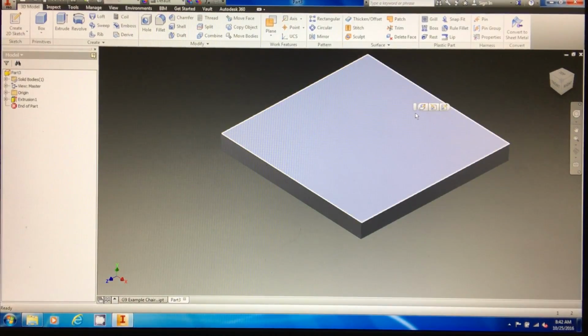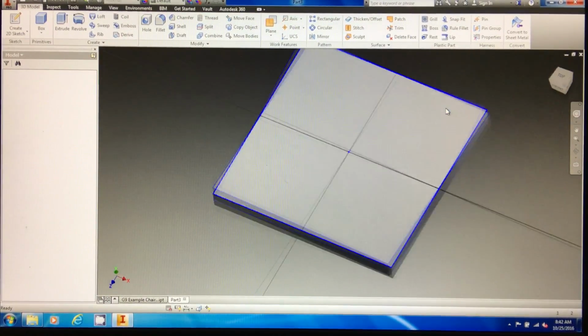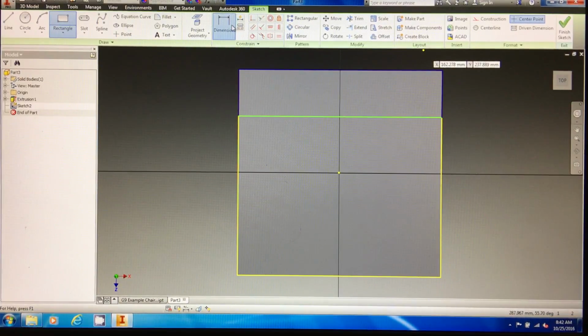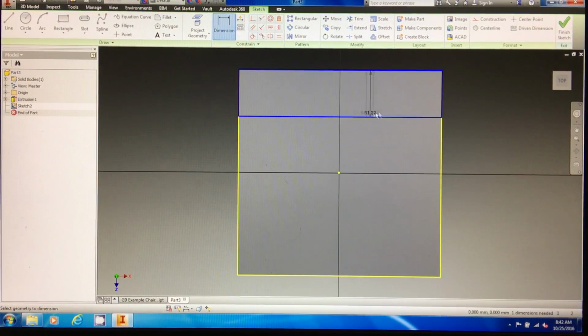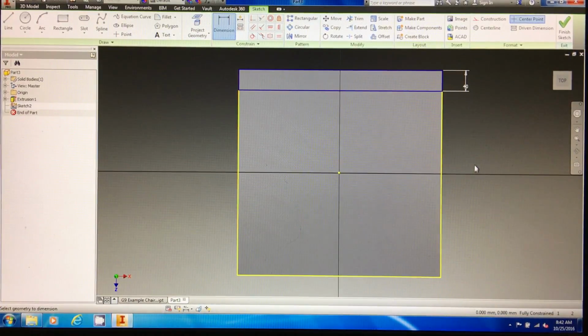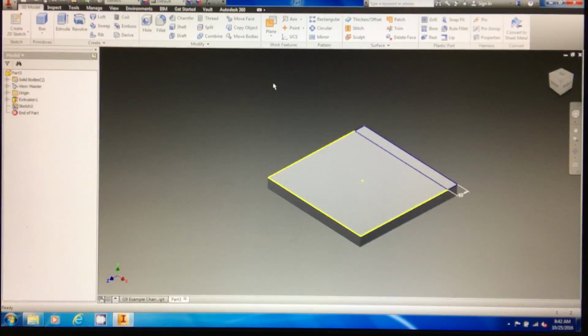Now this is the seat of the chair, so we're going to have a back going up here somewhere. If I click on this top surface, I've got an option to create a sketch. I'm then going to create a new rectangle, but this time I'm going to use the 2-point rectangle, the first option, and go from point there to around here somewhere. Now again, I'm going to set the dimension to 40 millimeters. You should be working in millimeters on this. Finish sketch. So we've got the seat and the beginning of the back.